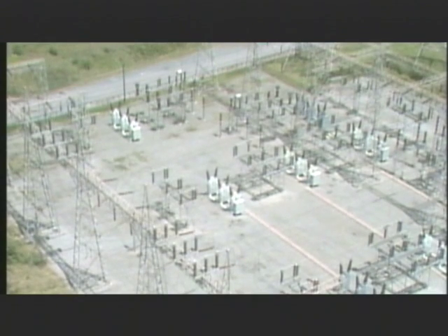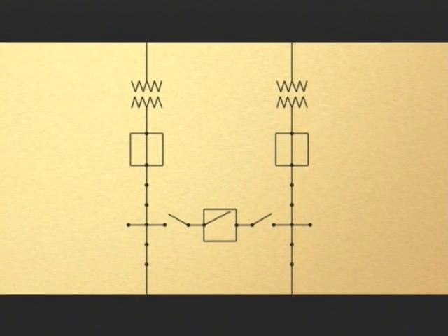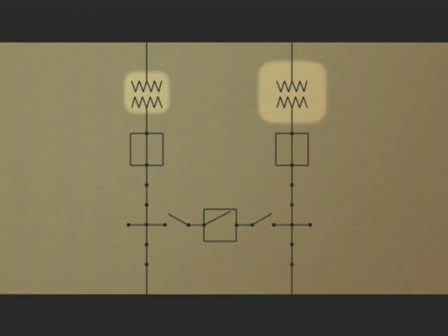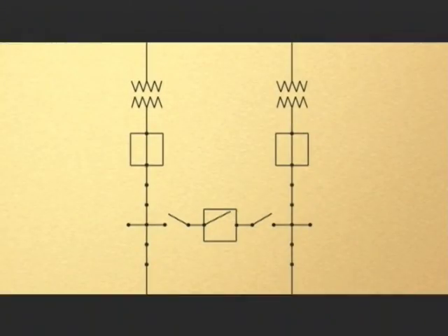Usually, we have several sources of power and several loads. In a switchyard like this one, we can select the source and the load in a number of different combinations. Now once again, to get an idea of how this works, we'll go to a simplified example. In this example, we're using single lines to represent the 3 conductors you'll see in actual switchyard circuits. Now these symbols represent unit transformers. Each one is a separate source of power for the switchyard.